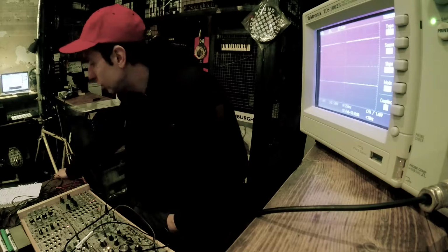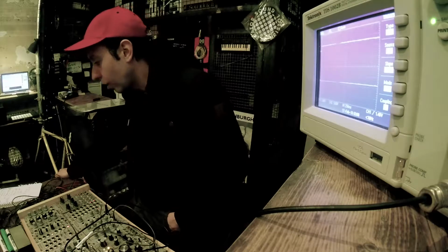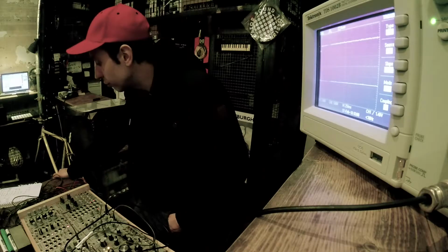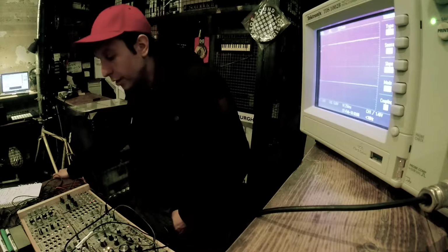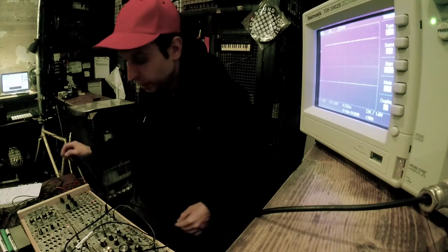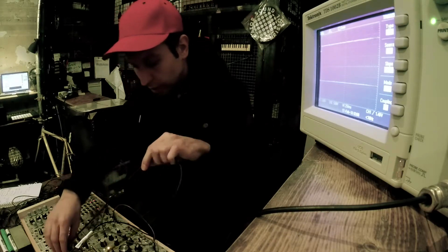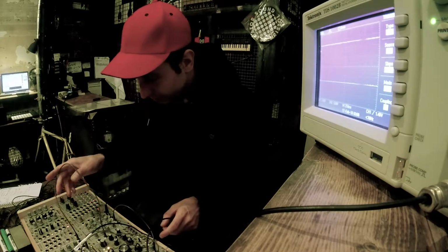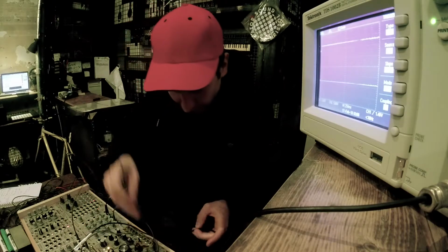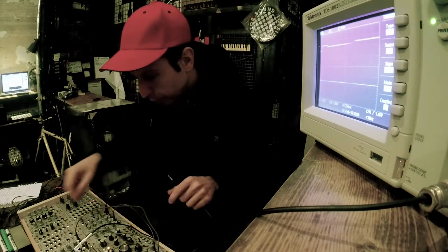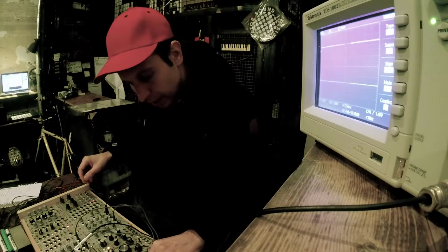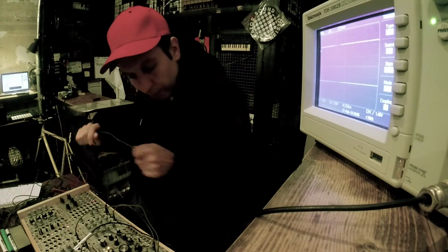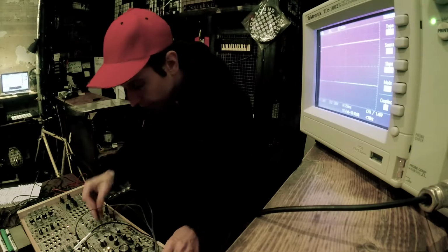Then the interesting thing, which I'm surprised people don't talk a lot about, whereas it's one of the easiest things to do, is cross modulation. So you use a VCA, you just multiply with the noise signal. Maybe this is something we could hear quickly. So I have put the VCA into the rack for today. I'm going to put a sine wave into my VCA, and then modulate the amplitude of that sine wave with my quantized noise signal.